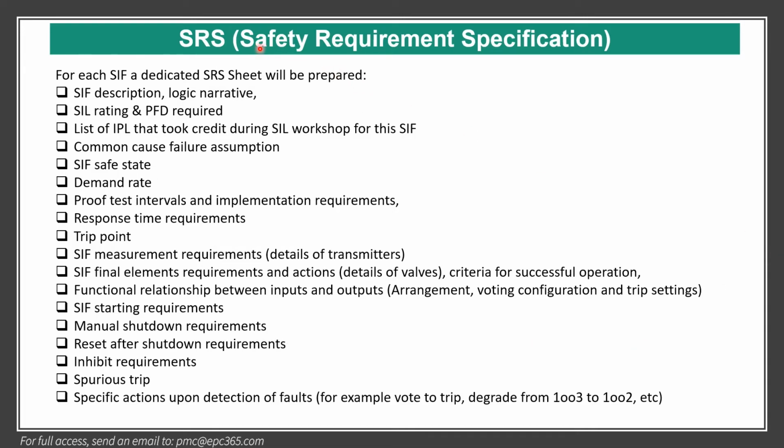So the SRS safety requirement specification will be prepared. These are the things that have to be there: SIF description, logic narrative, SIL rating, PFD required, list of IPL that took credit during the SIL allocation workshop. You can see in the SIL allocation e-course, common cause failure assumption, safe state, demand rate.